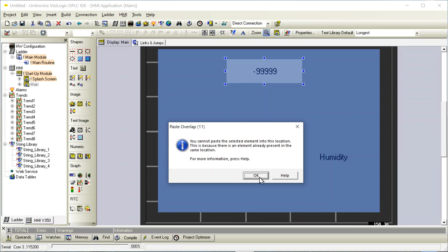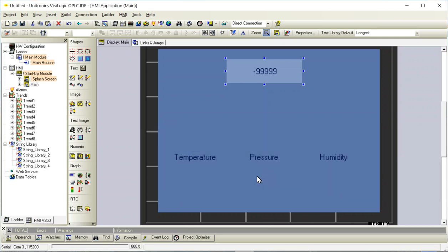And what we find out is that for things that change, and they're not text and not shapes and things, but for boxes that change and we have to connect them to something as far as associated with a memory location, you can't lay it right over top of the other one. So when you do your Control C, then you have to move that object just to vacate the area and do a Control V, and it'll put something the same exact shape with the same setup and properties in that same place. And that seems like a pain. It seems a little unnatural, but it ends up working well anyway.